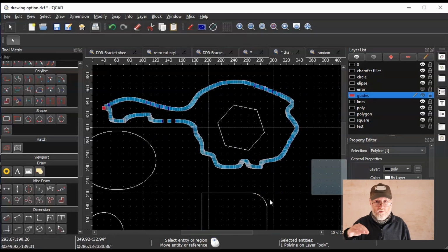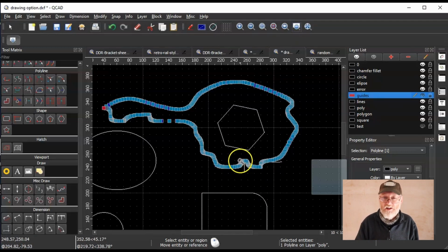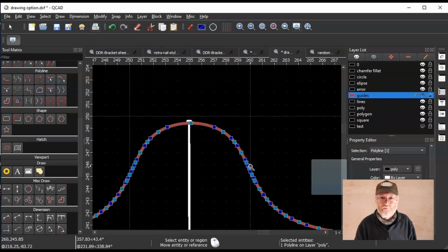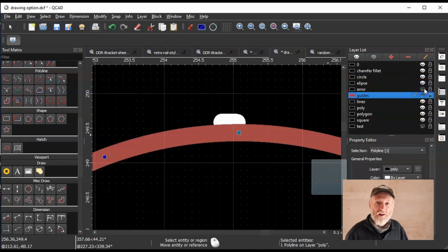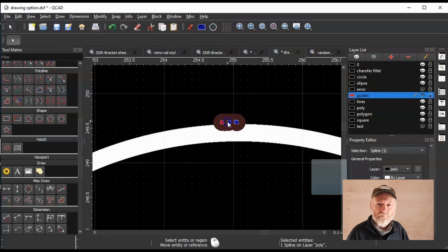Now when that dot is on the part itself or close to the part, it gets even harder to see. I've had to use arrows to show where I've drawn them on here to help me find them. If I was hunting for this manually, it could take me some time. That little pimple will cause all sorts of problems to the CAD software. It's a bit like having an unknown item on the self-checkout. Absolute pain. And these normally appear after you've done some kind of editing and you've sorted a curve or some kind of shape out, and it's left a little remnant. That little remnant just sits there waiting to cause you grief.